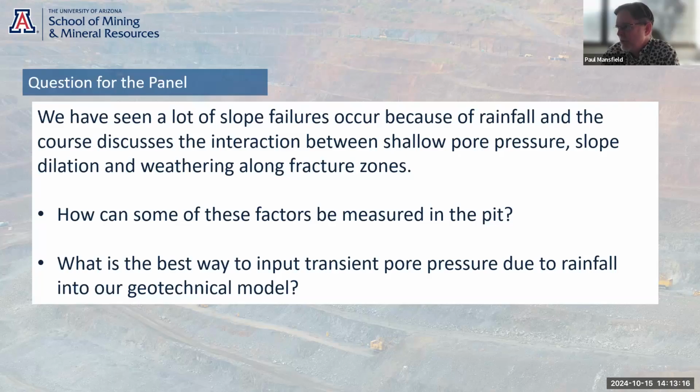If you put in the vibrating wire piezometers before, and you demonstrate that during certain times of the year, for example after the main recharge events due to snow melt or whatever, you're getting these increases in pressure, and the rest of the year the sensors are basically showing negative pressure, that helps you to explain why you need to put in some of these shallow horizontal drains to capture this shallow flow after these events. So it's key. You have to educate the people you're working with as well to get them on board with this.